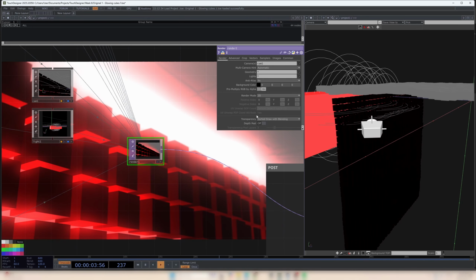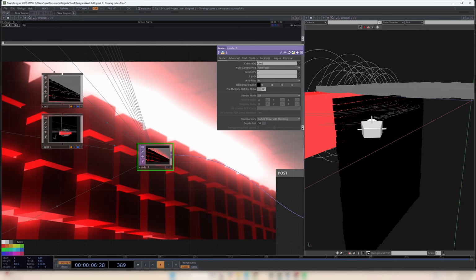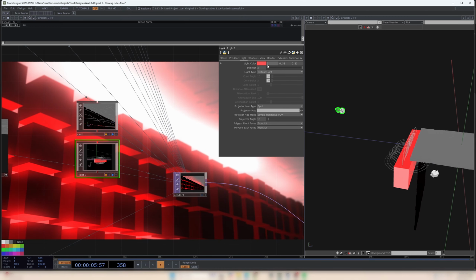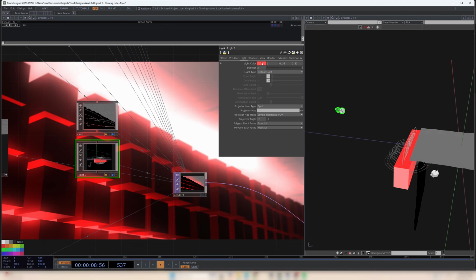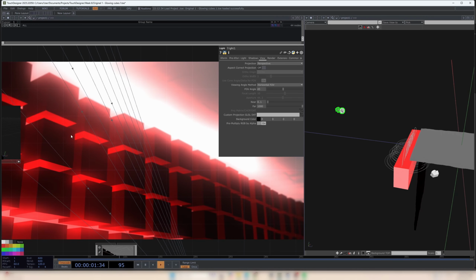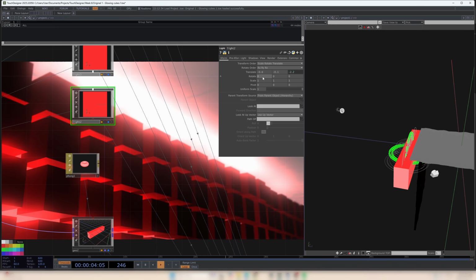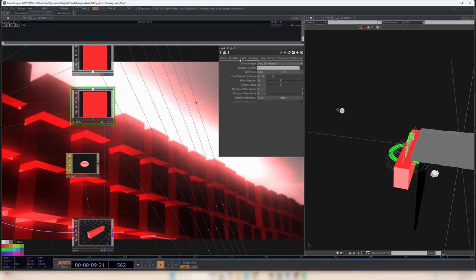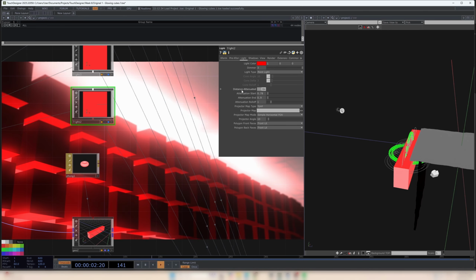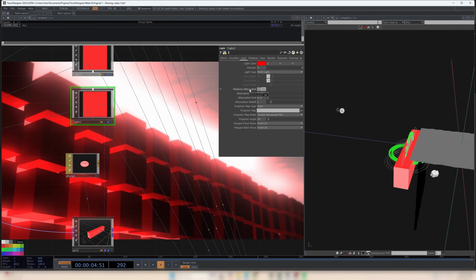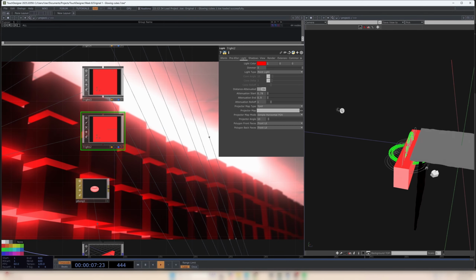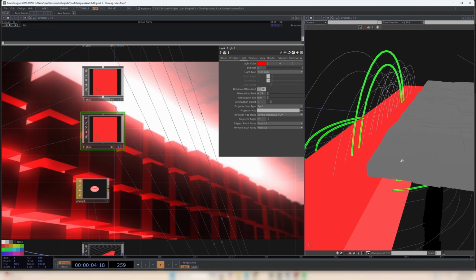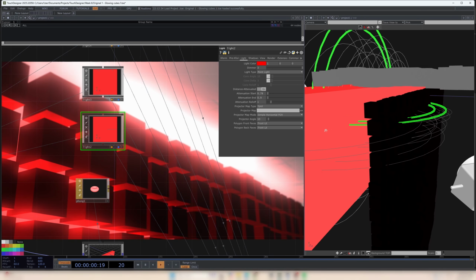This all feeds into the render sequence, no special effects here. This light is all the way out there. We've set it to a distant light, and it's also feeding us a red light. One thing to note about the lights up here is that we've played around with the attenuation settings, and distance attenuation has been turned on for those lights, because I wanted more of a glowing effect as opposed to a normal light. I think the attenuation affects how far that light spreads.